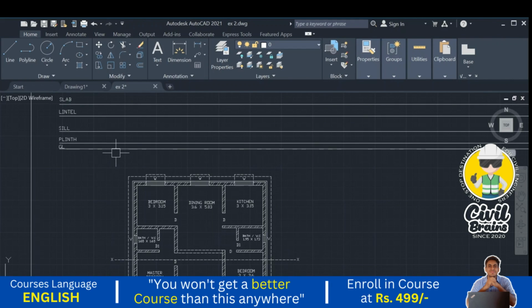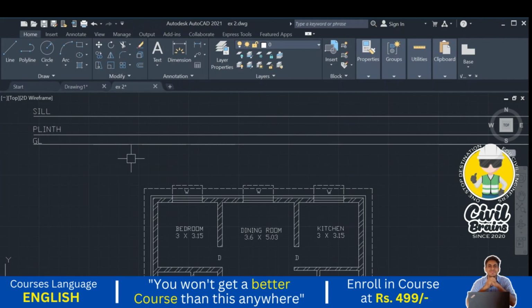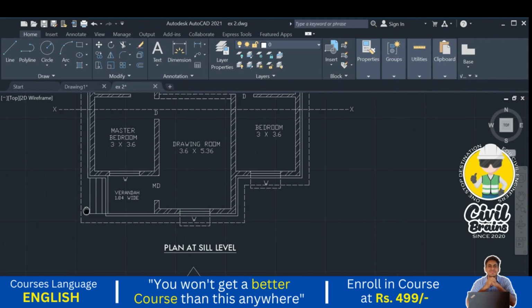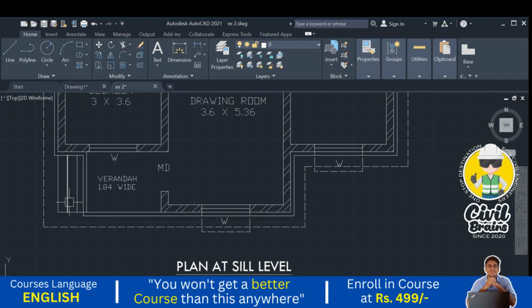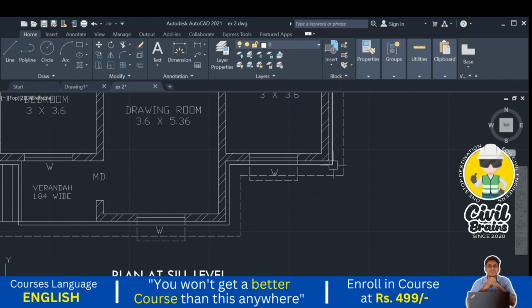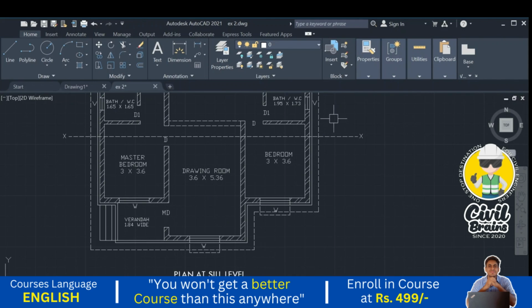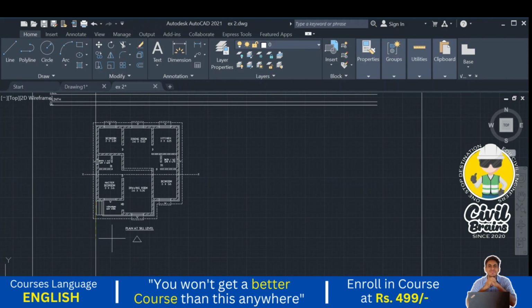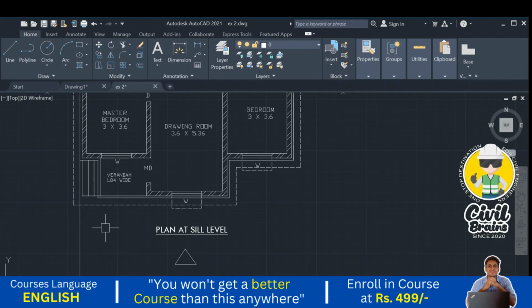Okay, so first ground level, zero level. Next one, what we need to find, we need to find the plinth. So you just identify where the plinth is here. This is your plinth corner, this is your plinth corner, this is your plinth corner, this is your plinth corner. All the plinth corners you just project first. So I go to the projection line or construction line, click here, I click on the projection in the upper direction, 1, press enter.